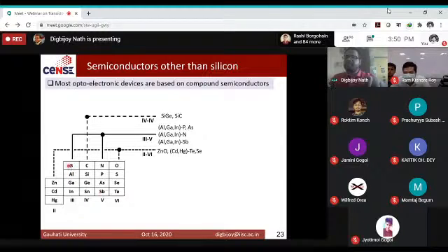You mix them, and you cannot randomly mix them, by the way. There are many rules there. You have aluminum, gallium, indium, phosphide or arsenide. For example, aluminum phosphide, gallium arsenide, indium phosphide. That's one family of semiconductor. Then nitride, aluminum nitride, gallium nitride. That's another family. Antimonide is another family. Or you mix group 2, zinc, cadmium, mercury, with group 6, oxygen, sulfur, so you have zinc oxide, cadmium telluride, mercury telluride. These are different semiconductors, not silicon.